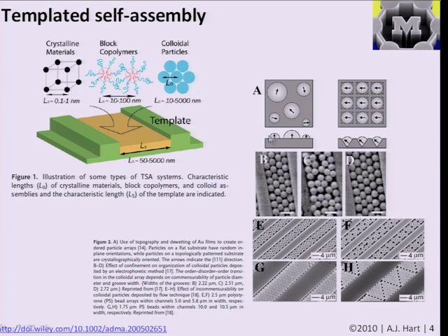So instead of having, for example, particles on a substrate that are essentially islands of metal, if you have a topographically controlled substrate, it's energetically favorable for the islands to sit down in these cavities, and because of the interactions between the cavity and the metal, for the islands to be of similar sizes. So these are kind of just two general approaches toward combining the ability to create features from the top down with the ability to understand how materials evolve from the bottom up.